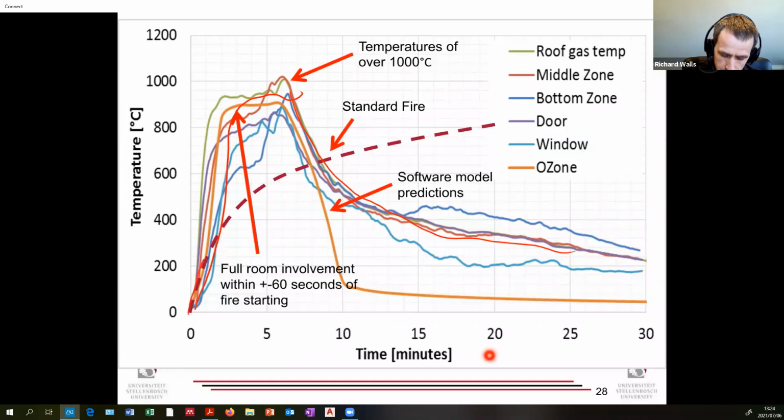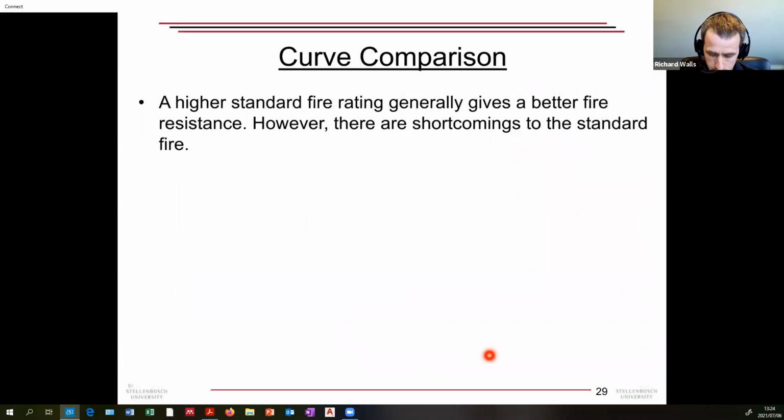The standard fire heats up slower, depending on your geometry, but then will continue on. This was a very, very small dwelling. But this shows the difference between a burnout fire, fuel load, ventilation, etc., and a standard fire, which is a time temperature curve. Remember, standard fire as a benchmark, burnout fire is actually considering of your actual structure.